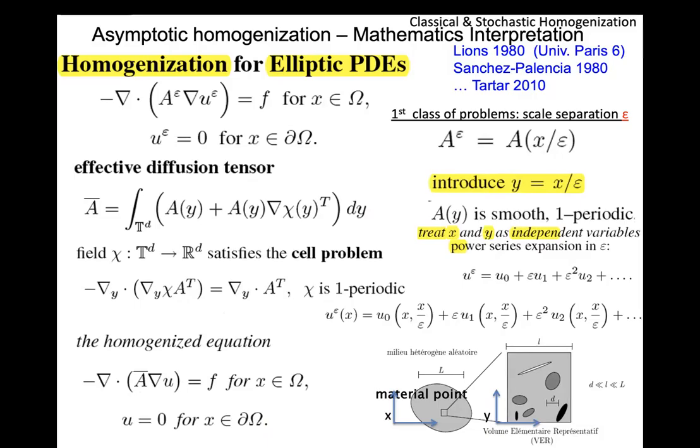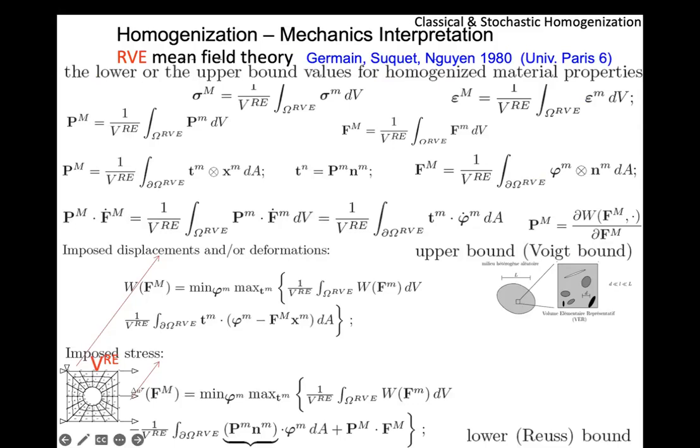Now, in the representative volume element, the situation goes as follows. You can take micro stresses as opposed to micro strains, and you can enforce either that the average of micro stresses is equal to some kind of macro stress, which is the one that is actually featuring at this single point of your macro scale, or that the macro strain is the average of the micro strain.